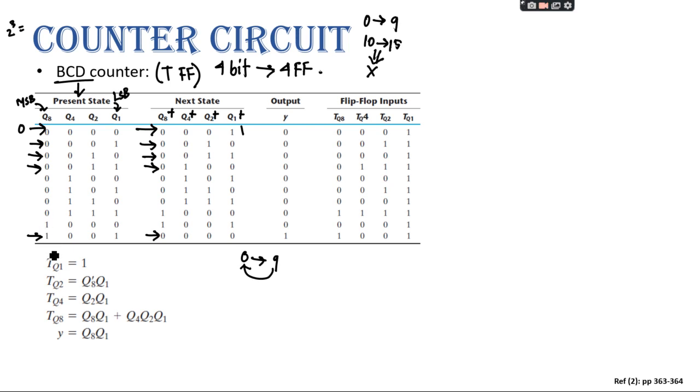So from here, as you can see, 1 0 1 0 all the way to 1 1 1 1 will be don't care positions for all, right? Because they will not be in use. So what is the truth table for T flip flop? Whenever you give 0, the condition will be no change, right? Yes, sir. And whenever you give 1, the output will be in toggle mode, the complement, right?